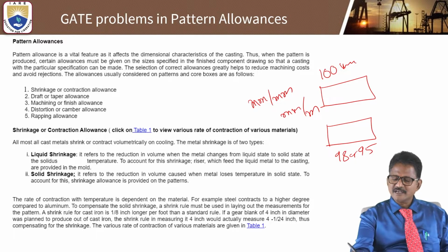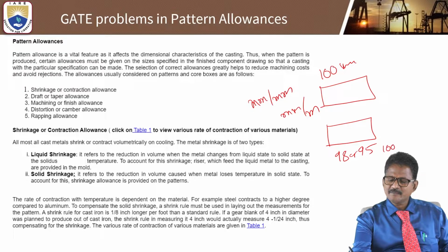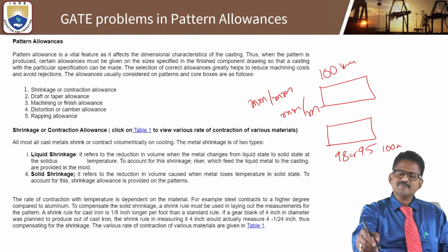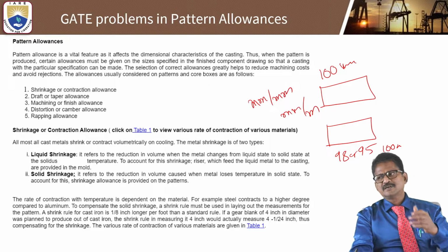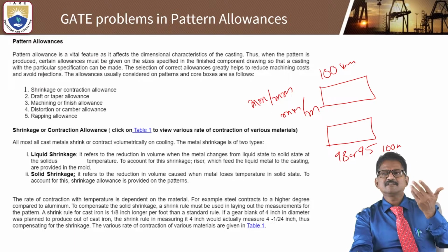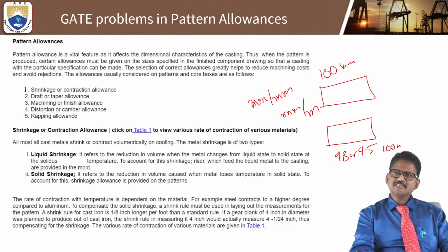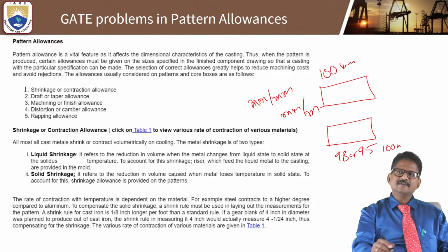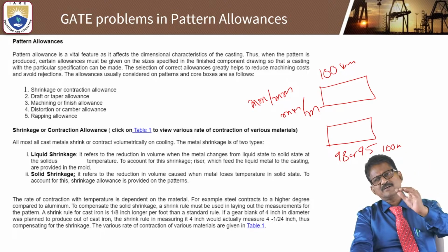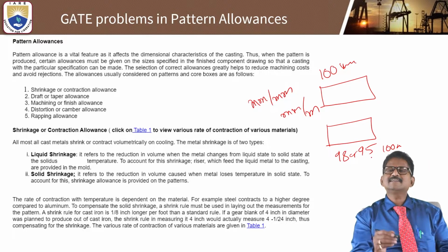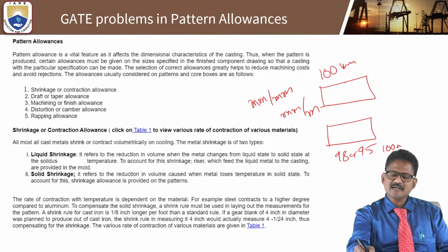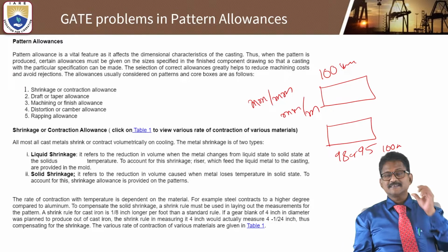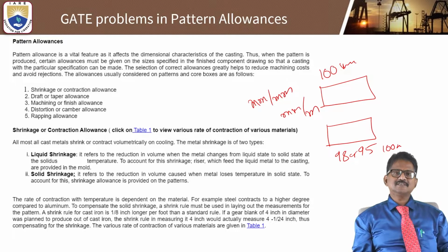When you want to achieve exactly 100 mm, we can add the shrinkage allowance for the particular material used, either mild steel, stainless steel, copper, zinc, or any other material. How much should be added? If you provide 105 initially, then it will come to exactly 100. If you use 100 mm, it will come down to 95, so the exact dimension cannot be maintained easily.